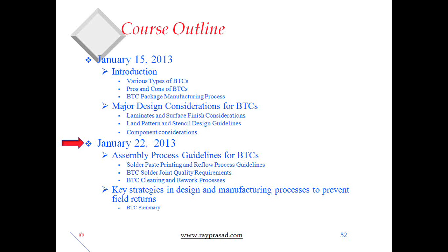And in terms of design, the land pattern design is critical. The pads are slightly bigger than the footprint. The spacing needs to be critical. There needs to be plenty of gap between the thermal pad and the land pattern, so there is no bridging.